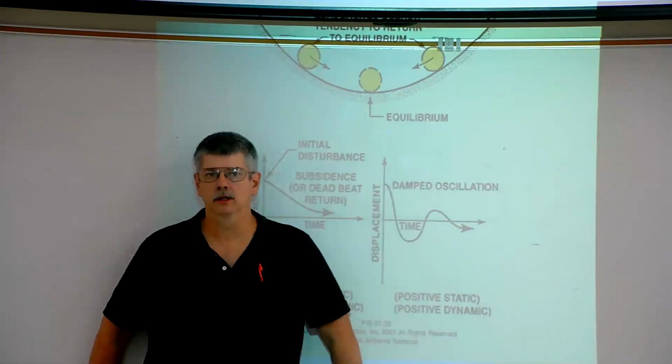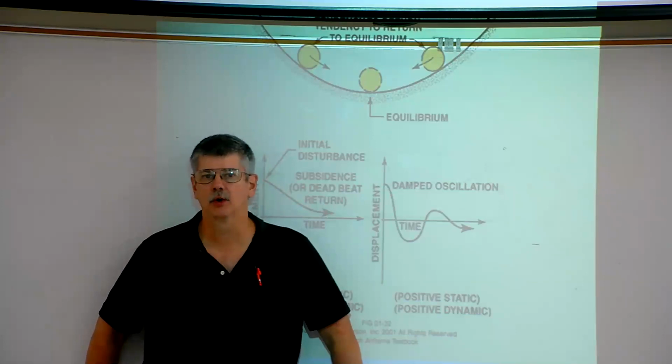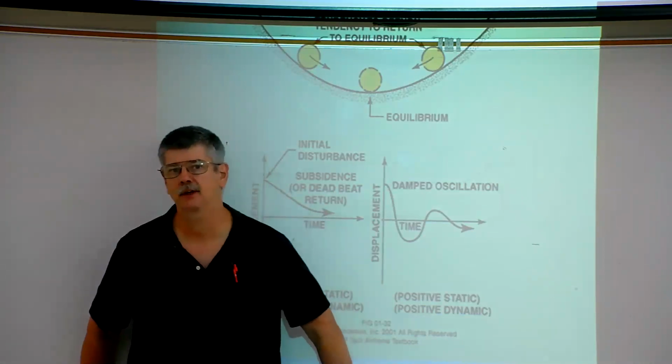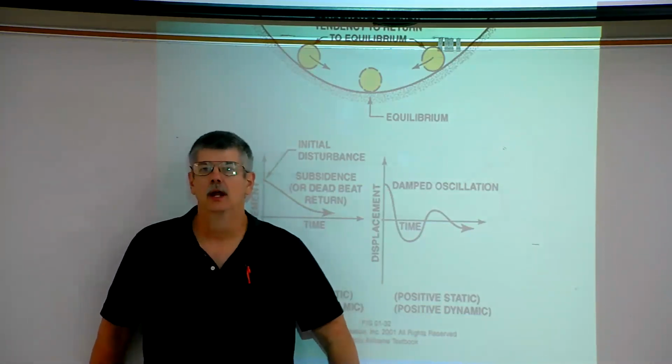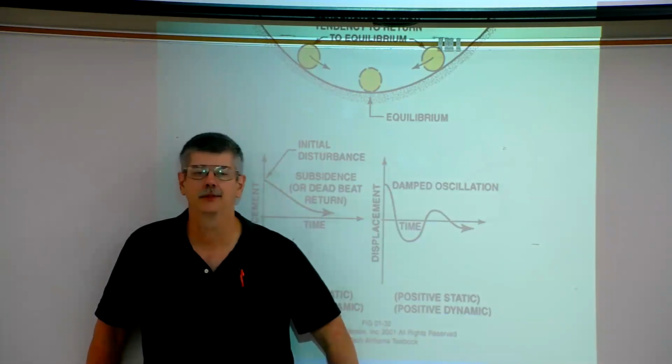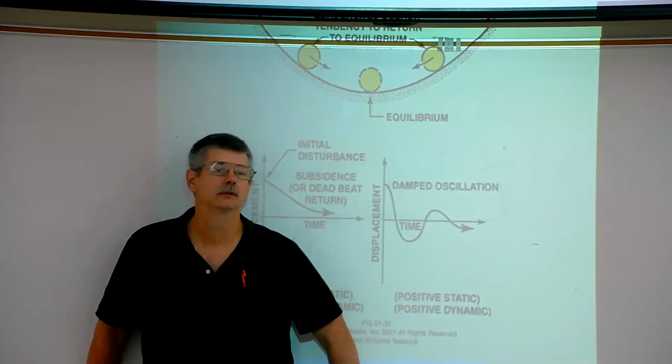The second way is what's known as a Frise aileron. In a Frise aileron, the hinge is aft of the leading edge. When the aileron goes up, the trailing edge goes up, the leading portion of the aileron will stick underneath the wing and thus create additional parasitic drag.